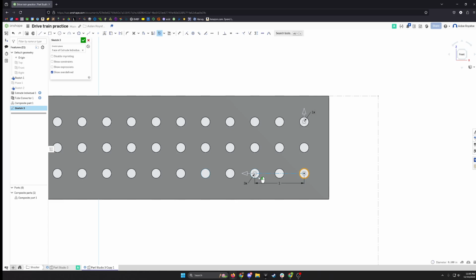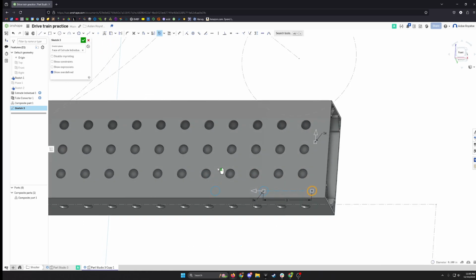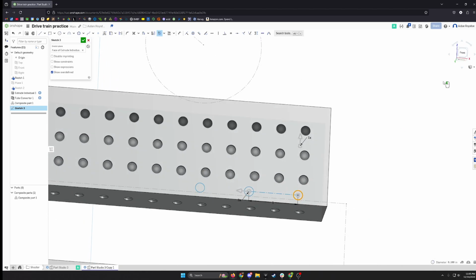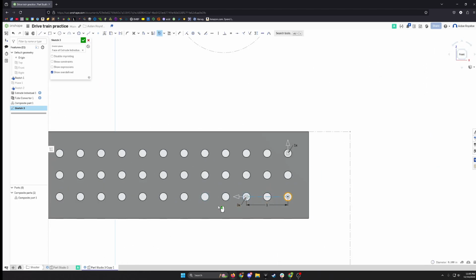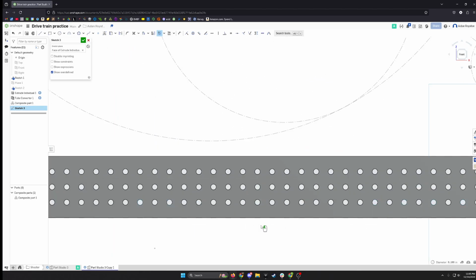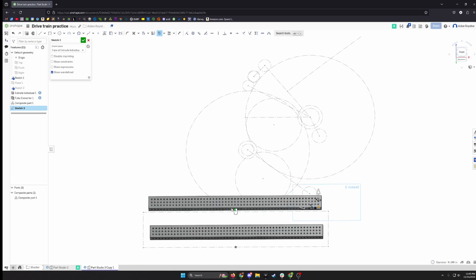And you can see it's started to generate more geometry. It's a little easier if you rotate it because you can kind of see where it is. And so we have all these holes, but we don't want to have every single hole be one. So this 1 inch distance is correct because these holes are on a 1/2 inch interval. And so we're gonna set this to, let's say, 15. Oops, not 145, 15. And you can see it ends about here.